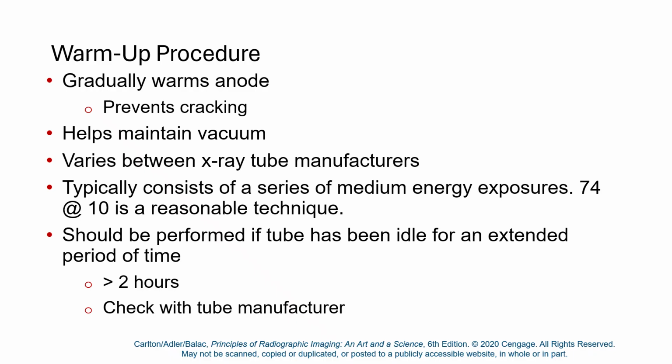Your warm-up procedure is to prevent that heat shock type thing and the cracking or shattering of the anode, because you went from ice cold to damn near molten in about 30 seconds.